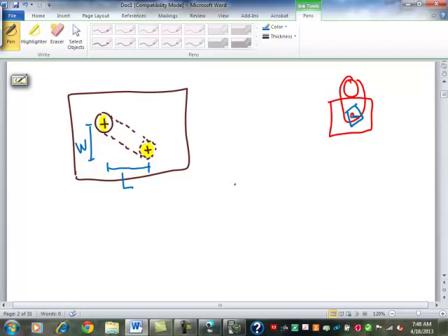You want the part to be situated such that this hole, the angle of this hole now goes perfectly side to side on the drill press. Now you can tilt the table so that that hole is perfectly up and down as well. So now once you got it rotated the right amount, you can tilt the table so now the hole in the block is perfectly aligned with that vertical drill.